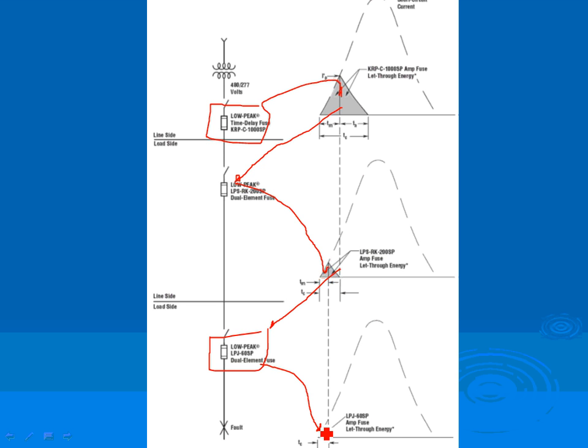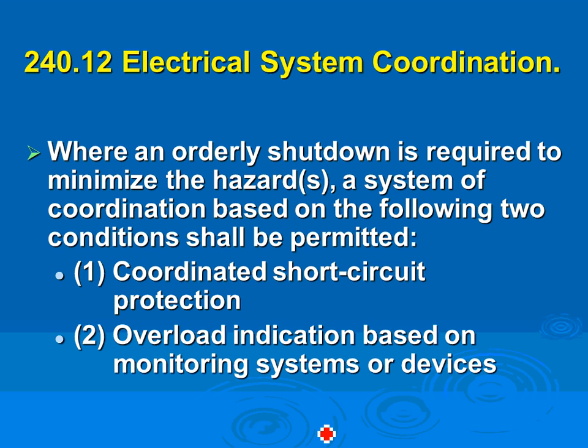Any comments, guys, about this? Any comments, any questions? So by far, circuit breakers are great if you have loads, if you have lighting load, receptacle load, they're superior, panels and all this stuff. When it comes to machines and protecting controllers, a lot of fuses are very good protection. Protect the VFDs and the starters and so forth. They're a better protection for your control system, so to speak. Any comments, guys? Any questions about that? Limiting it.